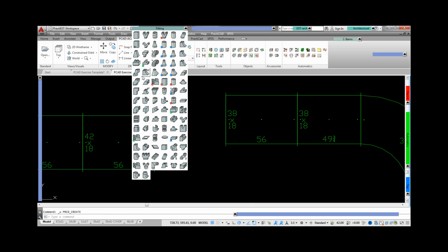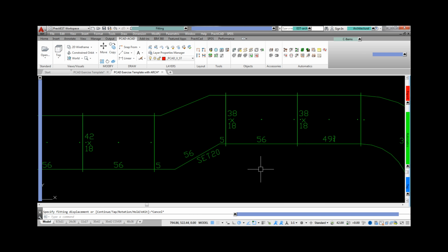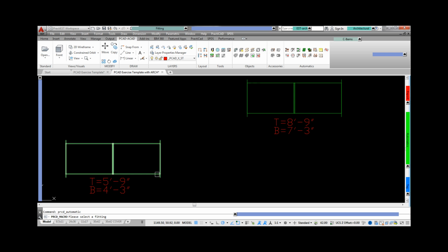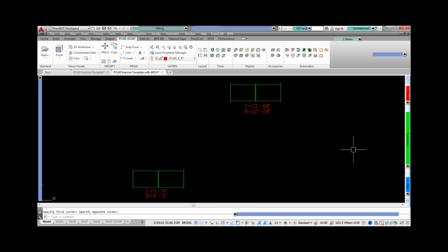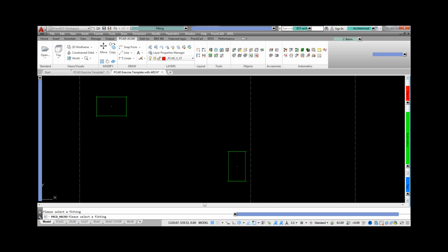Here you can see as we're using a few different types of transitions, including an extra straight and a double offset OG. In addition to what we call the single route, we can also choose to do multiple fitting routes. For example, maybe we would like to have 2 90-degree elbows equally routed between 2 pieces of duct at 2 different elevations. Perhaps we might want to route several pieces if there's a greater elevation difference between the ducts. We can use it for calculating sizes or turns.